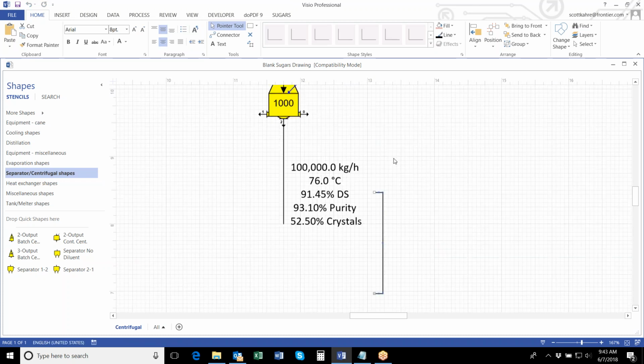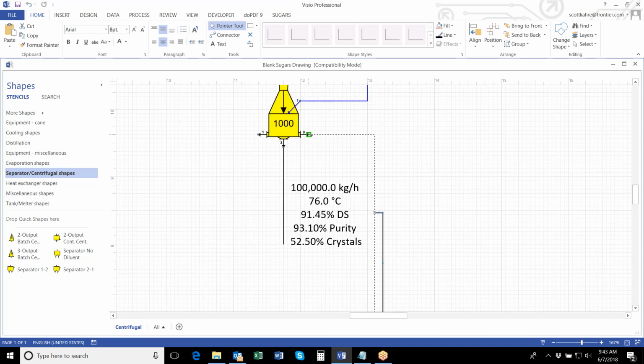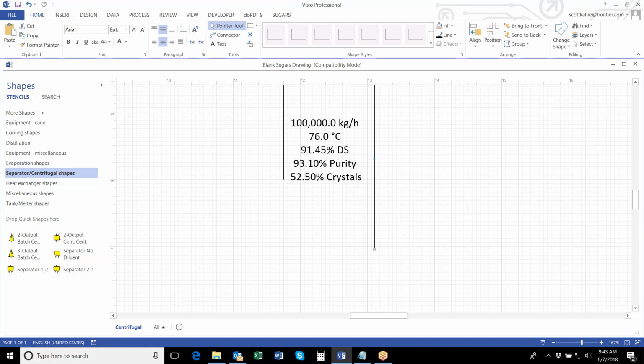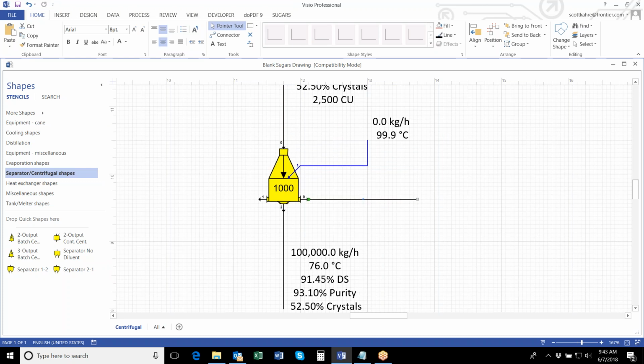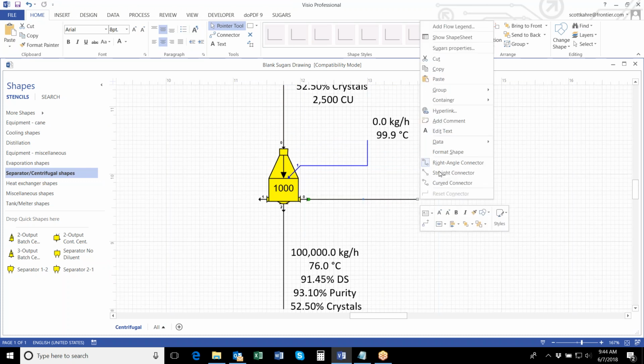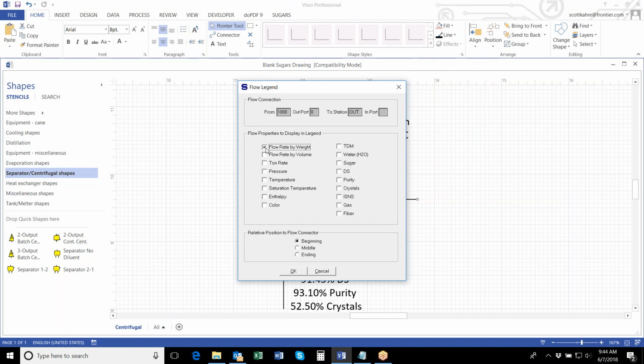and let's also put the green runoff. Control G. So I just pasted another one of those streams on there. Once you have a stream that's on the correct layer, and for output flows, you can just copy and paste it. Makes it a little faster. So this is our green runoff. I'm going to add a flow legend for it as well. Temperature.